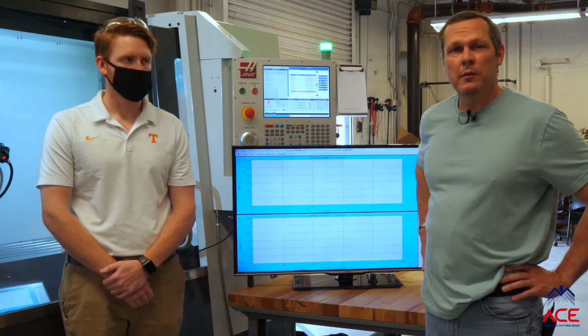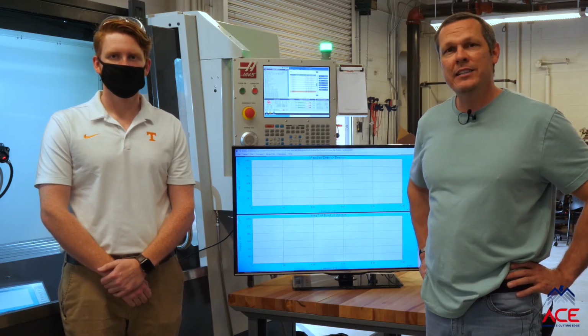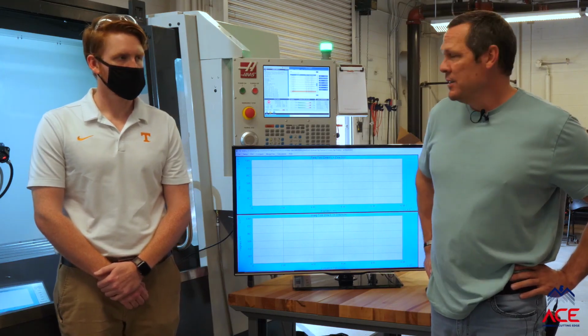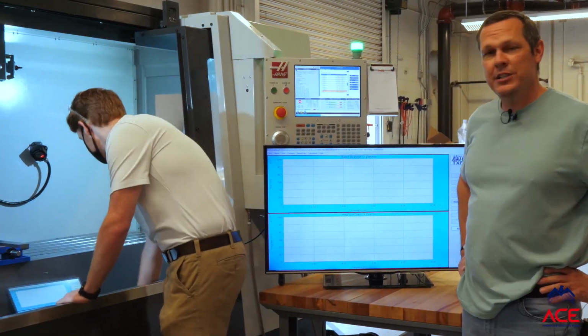the difference. The third part, we'll remove the workpiece from the machine tool and we'll look at it under a microscope so that you can directly see the difference in surface finish and why we want to avoid chatter conditions. Okay, so let's begin with the tap test. So Greg, let's start in the X direction.